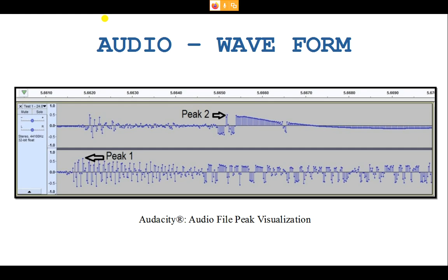On the top audio signal you might find a place where we have mentioned peak 2, that is where the first positive audio signal happened, which means the shock is passing through that microphone at that particular instant. So we basically found where these two peaks happened. There is a timestamp on the top x axis. So we took the timestamp, we found the delta t. We know the separation distance, calculated the Mach number, and found it to be around 1.1 Mach. So that is where these basic experiments can be done.